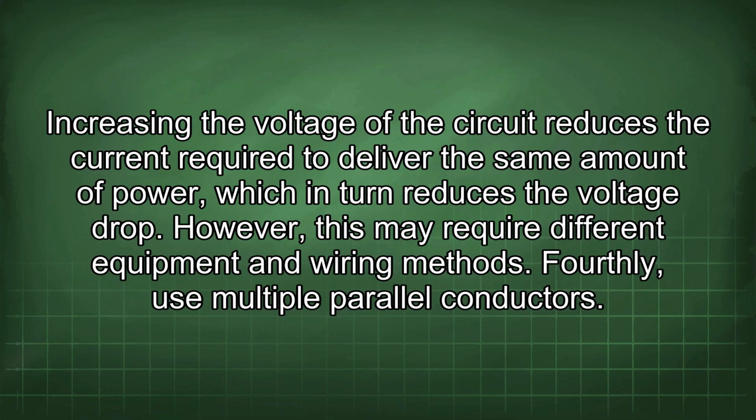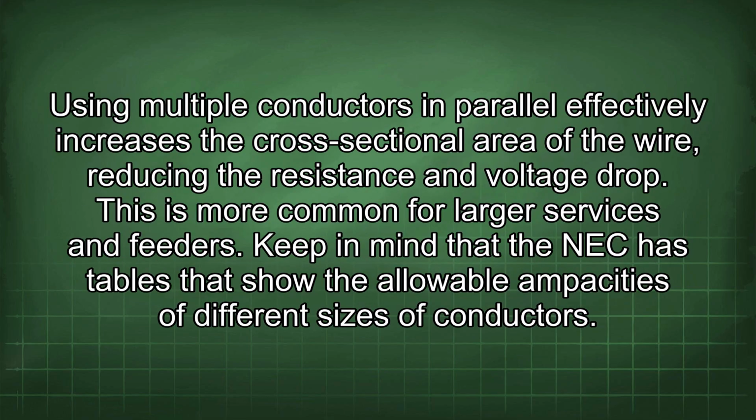Fourthly, use multiple parallel conductors. Using multiple conductors in parallel effectively increases the cross-sectional area of the wire, reducing the resistance and voltage drop. This is more common for larger services and feeders.